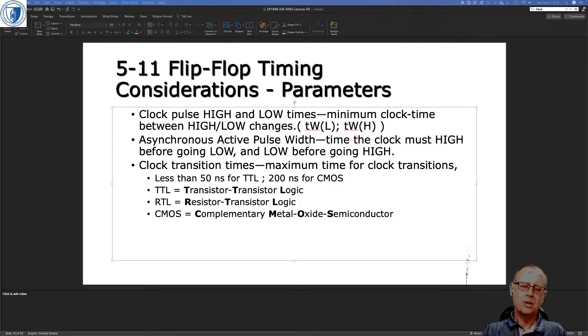When you're moving them from the storage in conductive foam to the actual device where they're going to sit, you don't want to touch the pins. You need to use tweezers or some other tool, an IC extraction or insertion tool, in order to move them around.